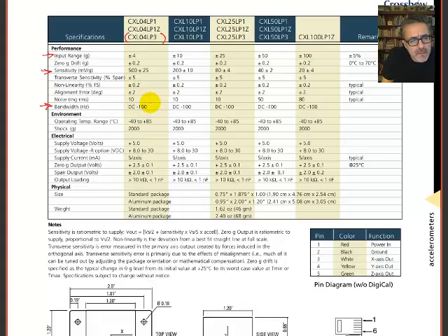And look at the units that they report. For our device, it goes from DC to 100 hertz. Okay. Do you know what it means when it says DC? Obviously, 100 hertz means 100 hertz, but what does DC mean? I want to explain that to you as soon as we start discussing this. When we talk about frequency at DC, it means basically constant. In other words, when we talk about vibration with a certain frequency, it means you're oscillating at a certain frequency. When you go to DC, it means frequency is 0. In other words, it's a constant acceleration.